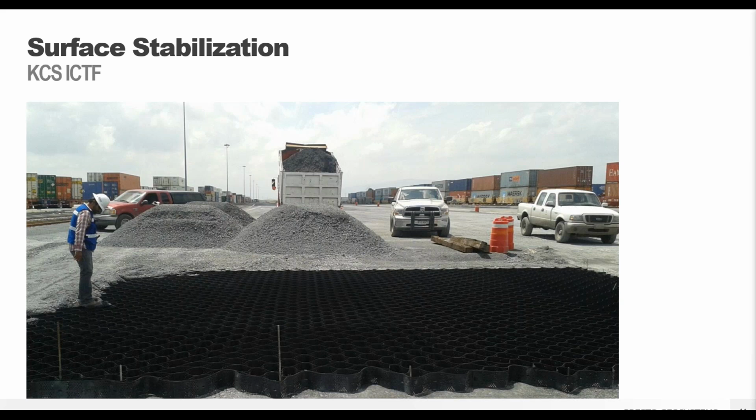And in terms of compaction of this material, you don't actually have to do significant compaction. So you push the stone into the cells, and then you have that wear surface, so that overfilling of the material over the panels. And as you're driving just your regular vehicles, or if you do want to put a smooth barrel roller compactor over the top of it, you roll that over the top, you drive over the top of it, and that vehicle movement compacts the stone into the GeoWeb panels themselves.